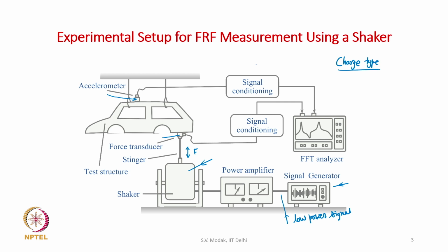then we require signal conditioners in the form of charge amplifiers, in order to convert the charge signal into a voltage signal, and then they are fed to the FFT analyzer.